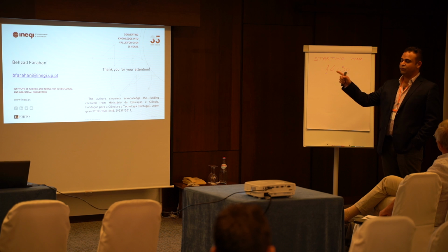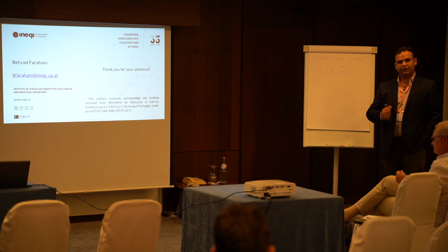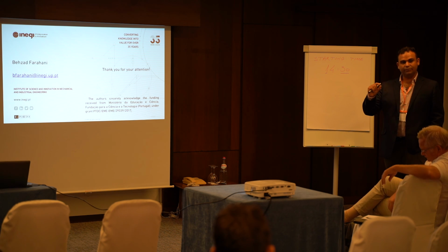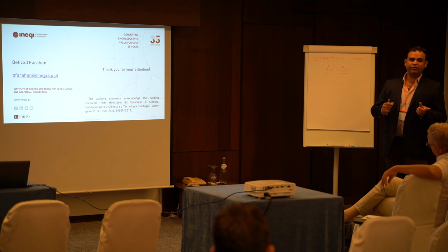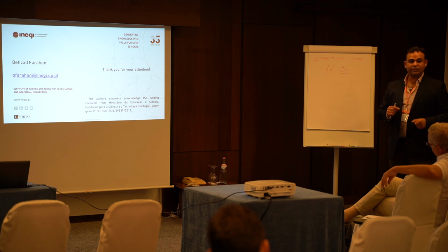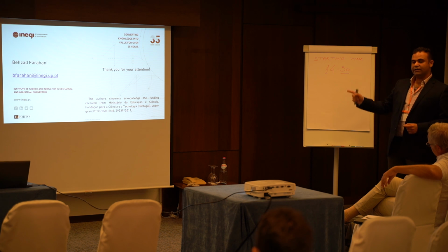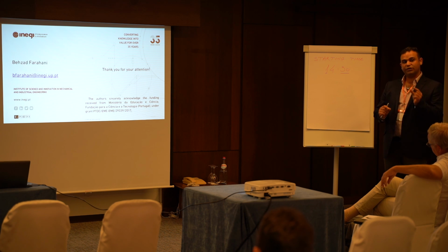I supposed that when I have a fully longer crack, the crack closure should be most visible and better assessed. But it was not like that, because of the plastic effect that dominated on the crack flanks and doesn't allow the crack to close. For the shorter crack, the scenario is different. We have less plastic effect, but we need to be very careful with the stress ratio, because the stress ratio was 0.1. I have already made another study with 0.05, and it was a better illustration of the crack closure for the shorter crack.